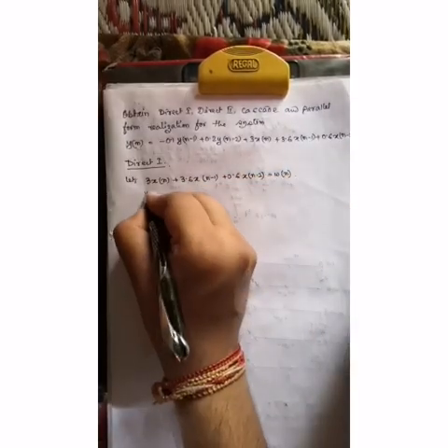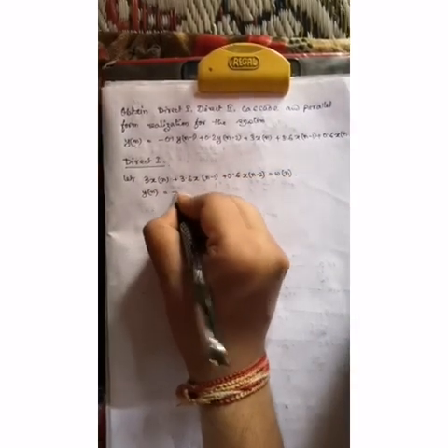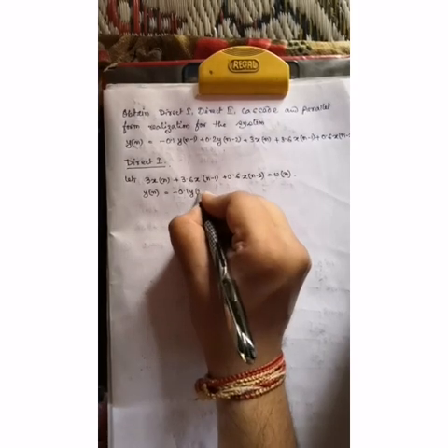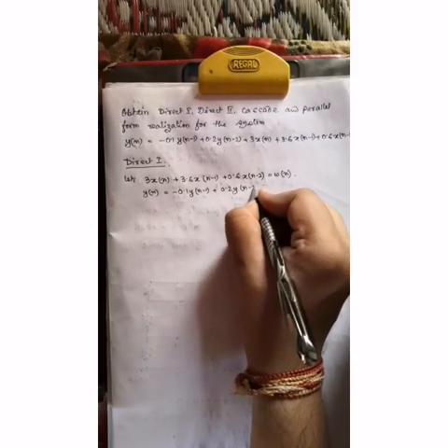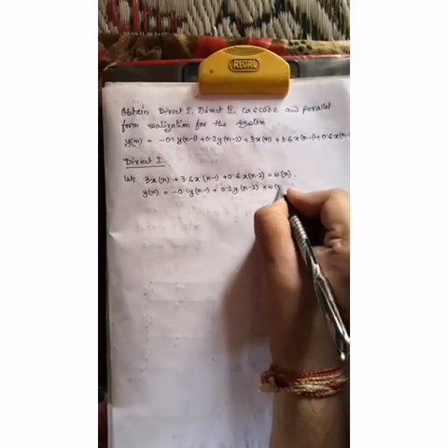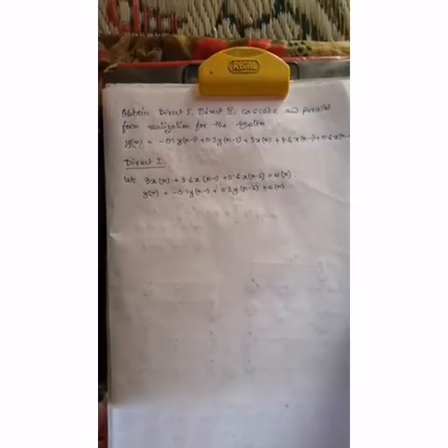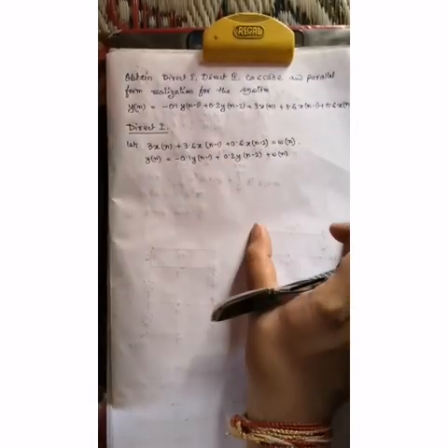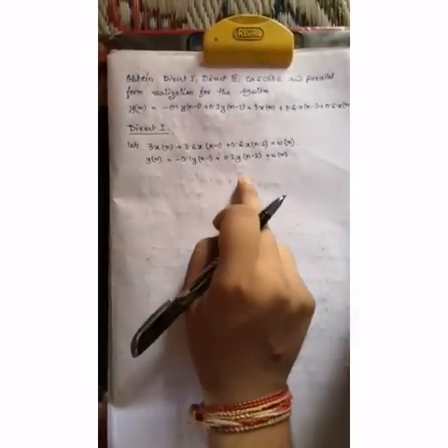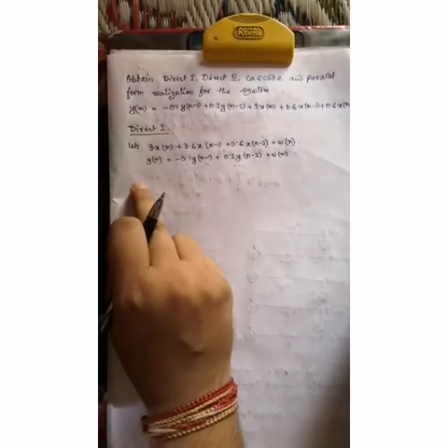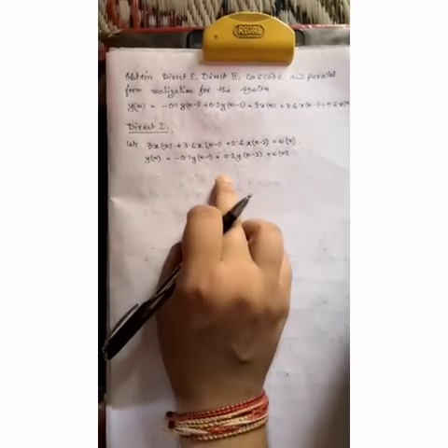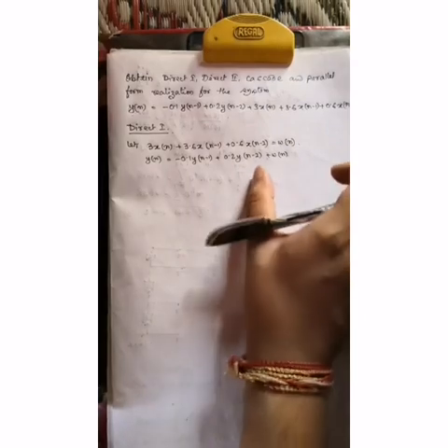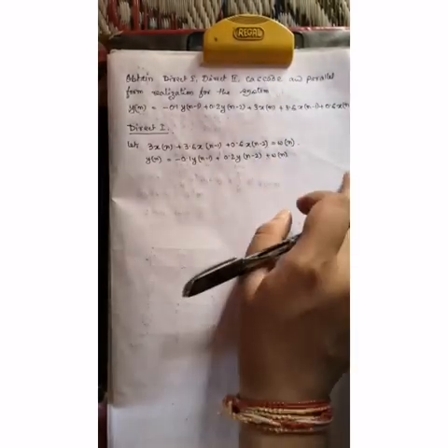That means yn becomes minus 0.1 y n minus 1 plus 0.2 y n minus 2 plus omega n. So now we have to draw the diagram. This part is for the xn, this part is for the yn. Input, output, intermediate is the omega or the w. For the first part, input is x and output is w. For the next part, w is input and output is yn.